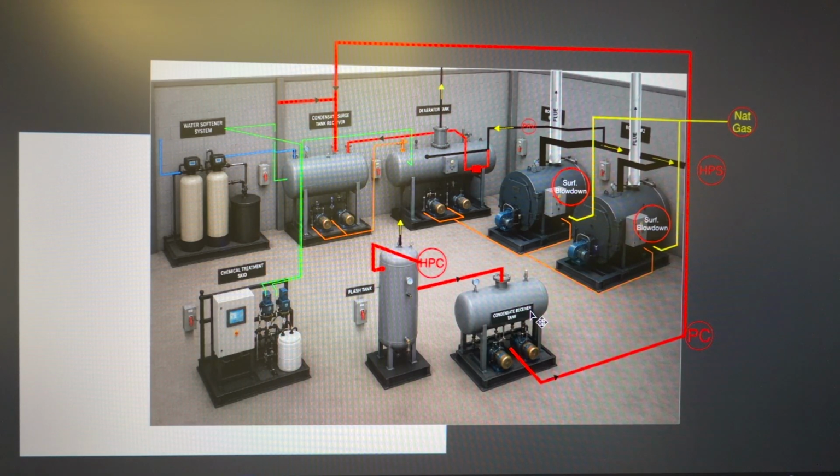The purpose is to collect returning condensate, store condensate until pumping is required, supply water to the deaerator or surge tank or boiler feed system, recover heat and treatment chemicals, and reduce makeup water requirements.